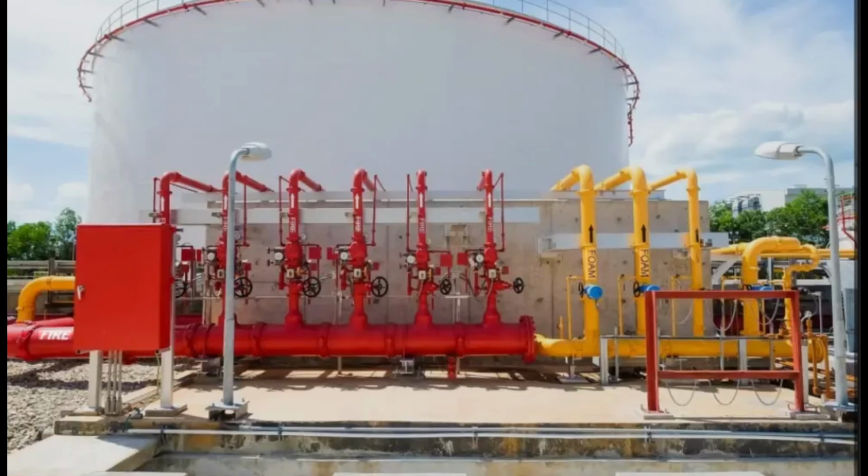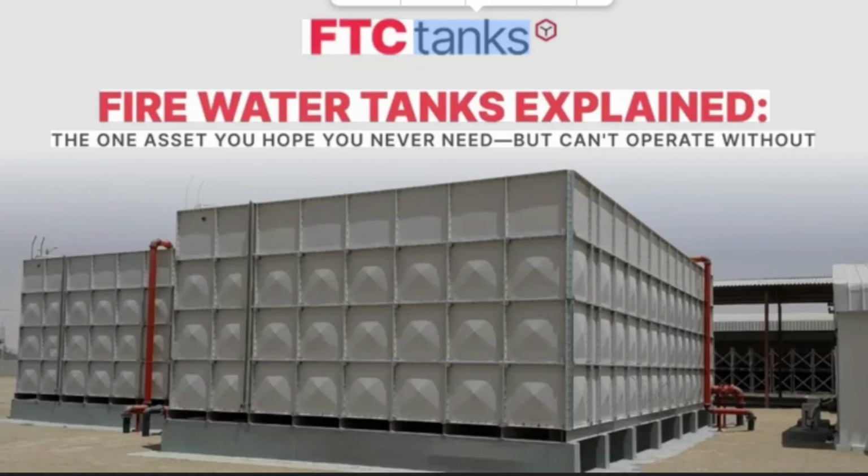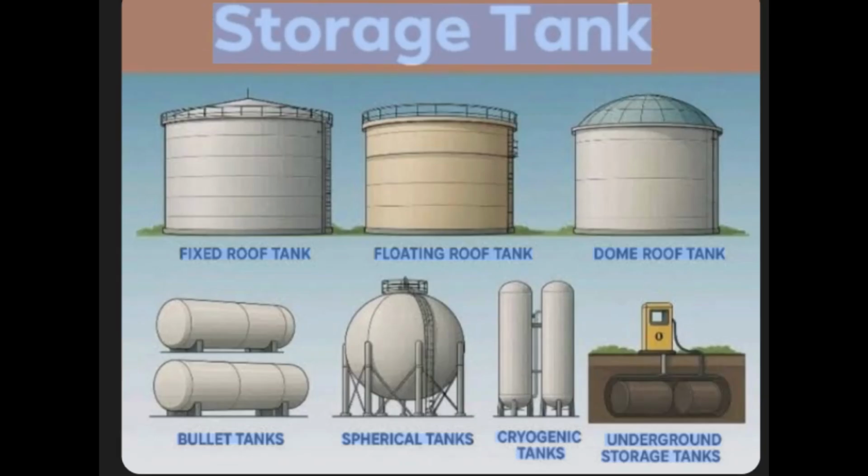4. Water supply conditions. You must know: is municipal water available? Does it provide enough pressure? Is a dedicated fire tank required? Where will the tank be located, underground or on roof? Large hotels always require a dedicated fire water tank.